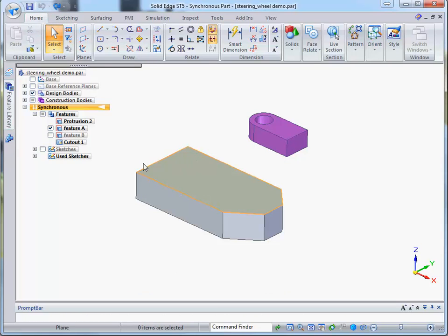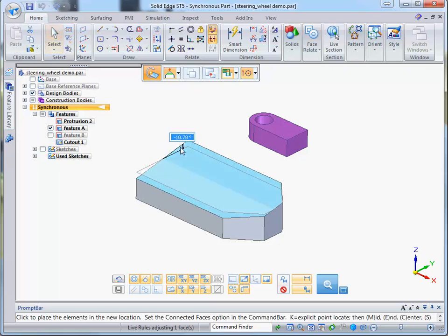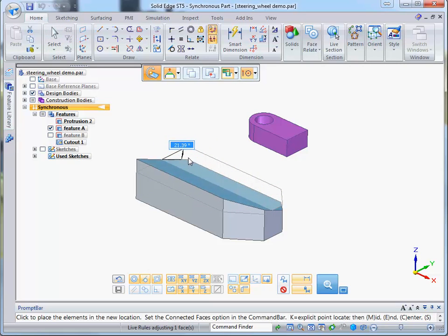Now let's say I wanted to rotate that face around a midpoint. What I would need to do is move it to the edge, and that will help me to specify the orientation, the rotation plane. But what I need to do is move it to the side. But you'll see how it reorientates itself. So we need to override that. The way we do that is to press shift before hitting the origin, and then I can move it over. So now clicking on the ring on the torus, it will allow me to rotate around that midpoint.